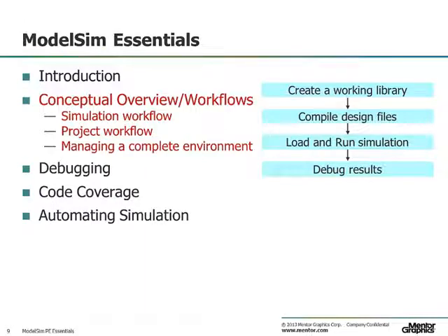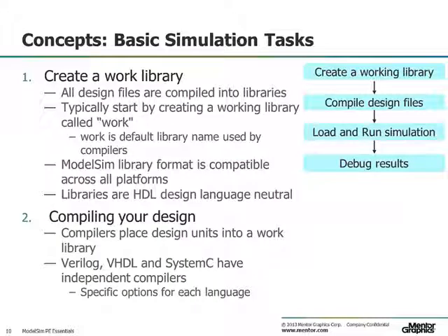There are two main methods for managing your environment: the traditional command-driven workflow and a graphical user interface-driven project workflow. We will also talk about how to manage the most complex simulation environments, so that once you've determined a workflow, you can then manage and add to that workflow. Let's begin with the basic simulation workflow. First, you create a library, then you compile your design, then you load and run simulation. And if you're like most people, you end up debugging the results of your simulation runs.